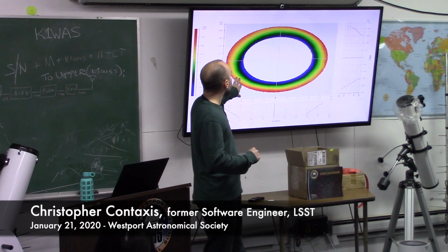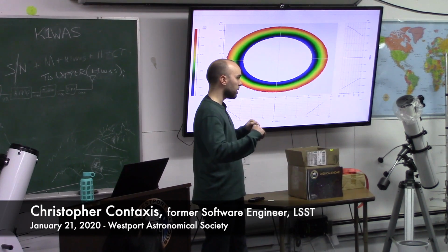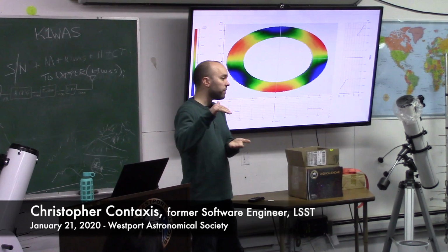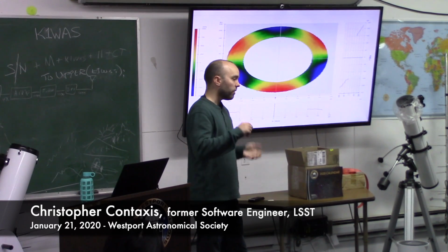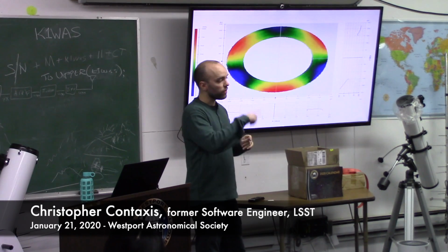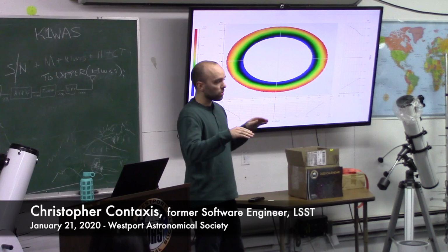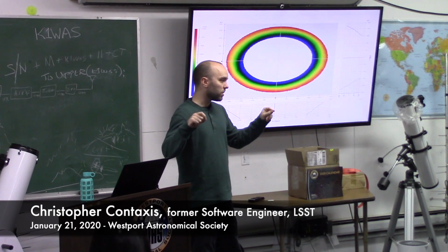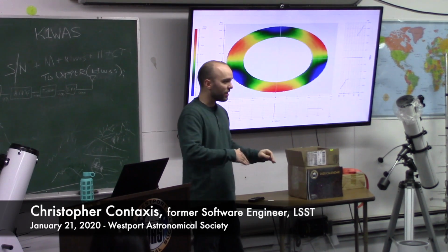So all 156 actuators have to reach their new target at the same time, right? If some actuators have to change maybe only, let's say, 5 newtons, others have to change 50 newtons, right? The actuators that change 5 newtons are going to get there first compared to the 50 newtons ones. And that force offset, that unbalanced load, would then go to the hardpoints, which would then deform your image or reduce your image quality. Then they would eventually correct, and that would go away.